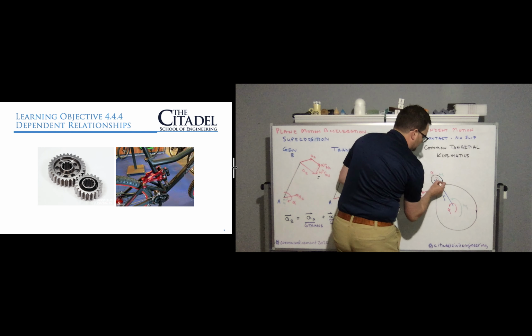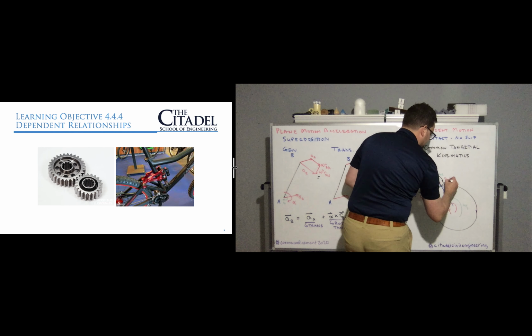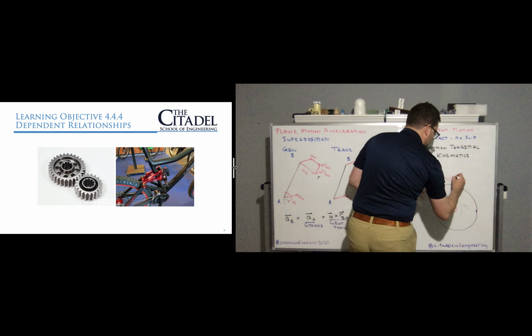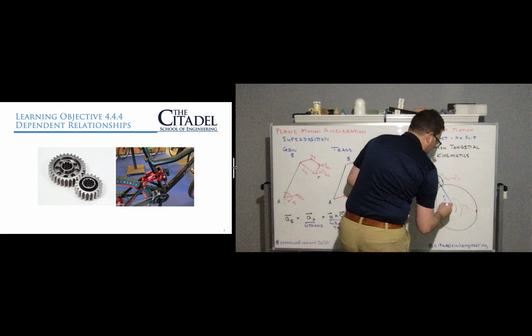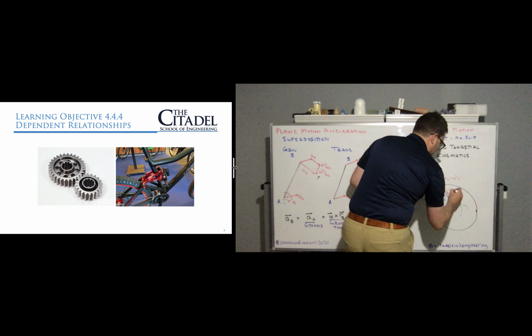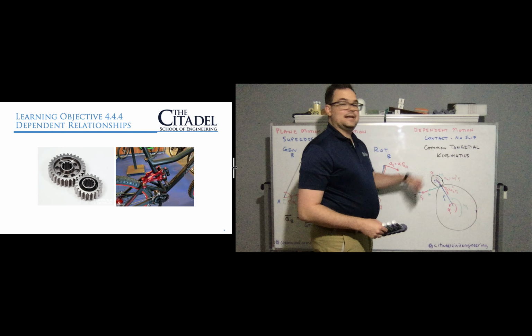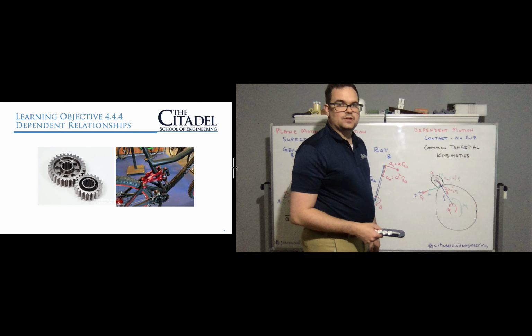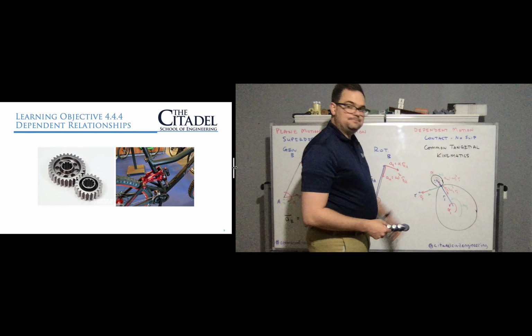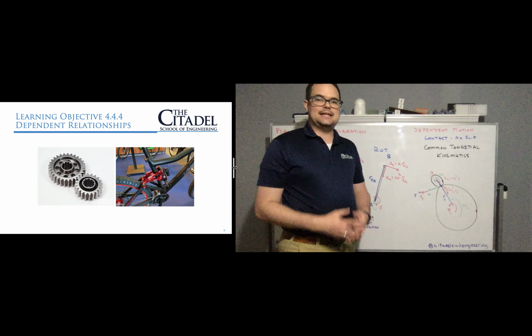And so we're going to have 2 different normal accelerations, omega squared times r, and a different normal acceleration of omega squared times r. So that's the difference between the 2. Velocity, it's all in the tangential direction, so we have common tangential kinematics. Acceleration, we only have that common tangential portion of the acceleration in a contact case.